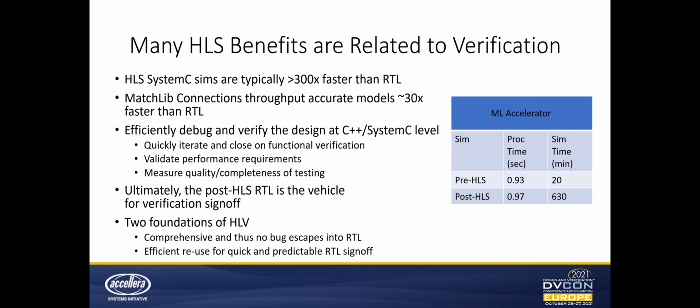These gains in performance versus RTL simulation are fundamental to why HLV can be so powerful. The ability to run simulations so much more quickly enables more comprehensive overall verification against that pre-HLS design. Now, we do recognize that RTL verification sign-off is still very much a requirement, but we want to do whatever we can to make that RTL level verification as easy and as predictable as possible, and performing as much of the design verification as possible against a faster version of the same design helps to ensure that predictability.